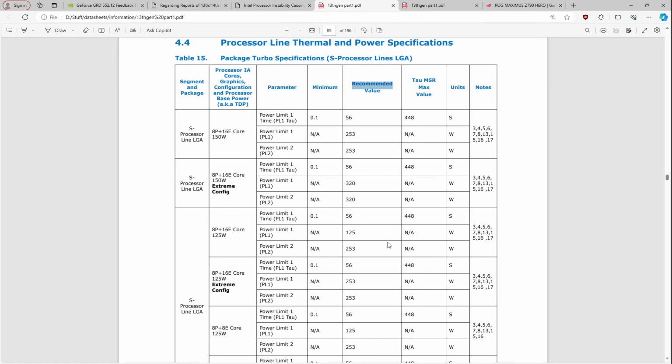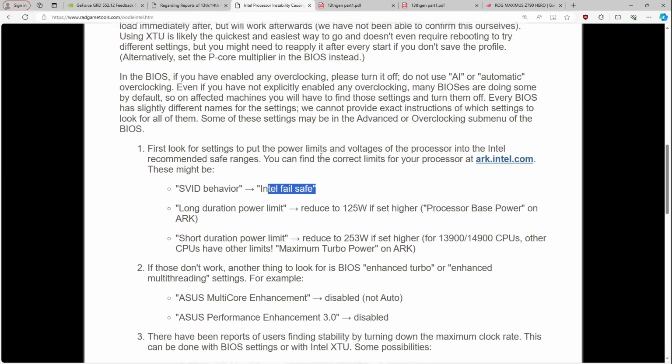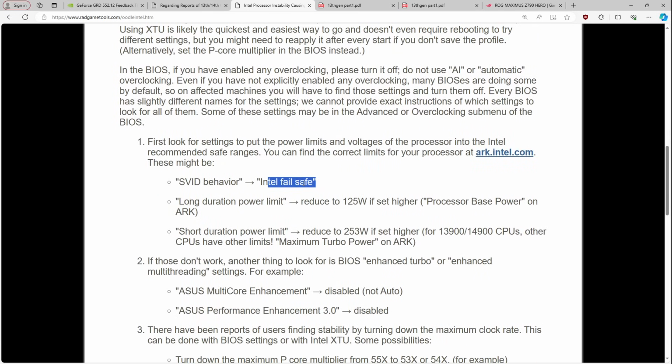Now, as far as the degradation is concerned, if you want to avoid it, I'd say the best way is to just lower the temperature limit, because there's sort of two flavors of degradation that you get. At high voltages and high temperatures, you can have electrons just kind of punching through things that they shouldn't be going through. This is very bad. It will generally kill things extremely quickly. I don't really think that's what's happening here, because that would basically break CPUs, generally speaking.